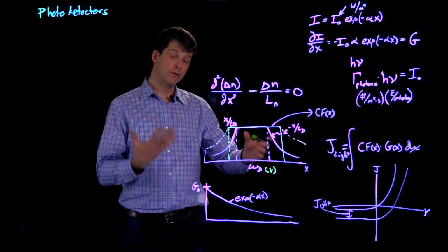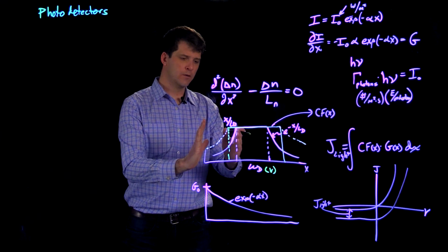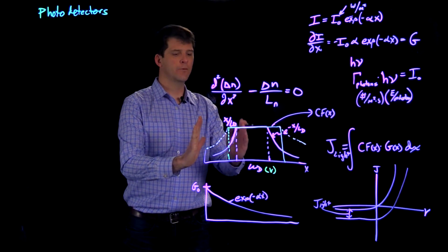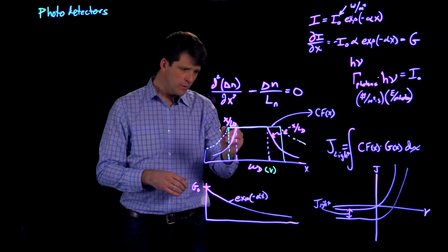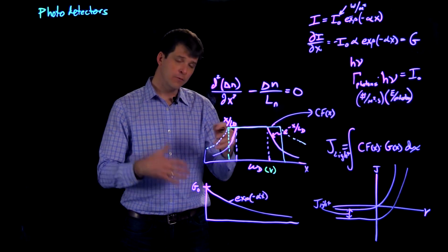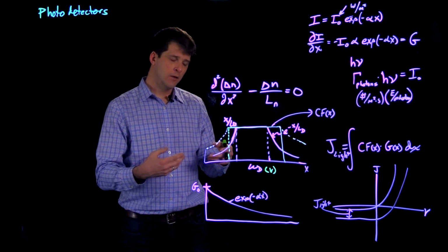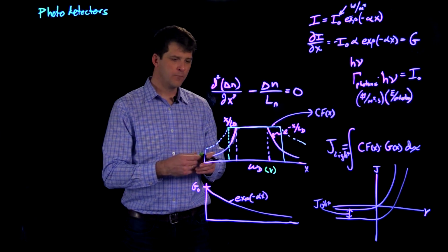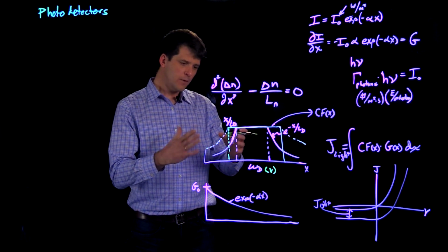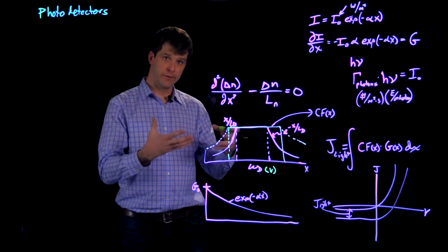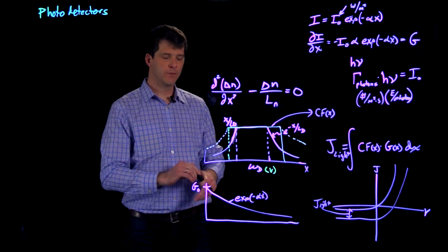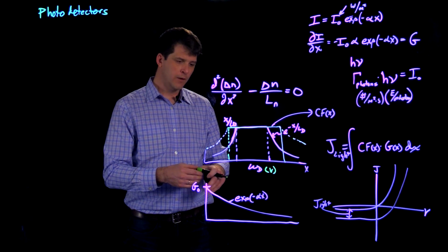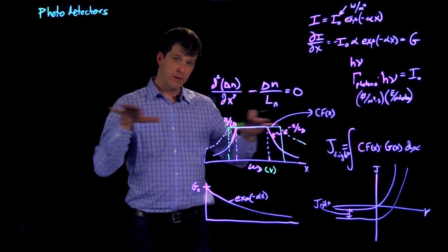This becomes hard to do because it takes a lot of voltage to move the depletion width appreciable distances. So what you'll end up doing is eventually applying enough reverse bias that you would start to have a large dark current, and thus the detectivity of the diode would go down because you'd have a large background current.